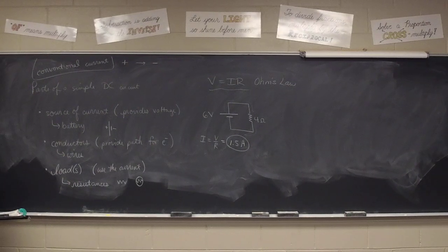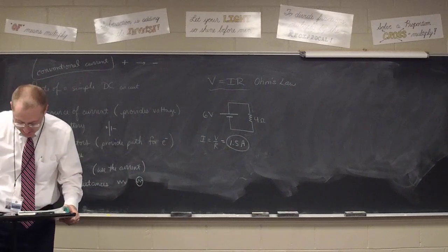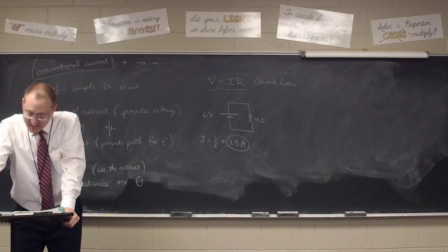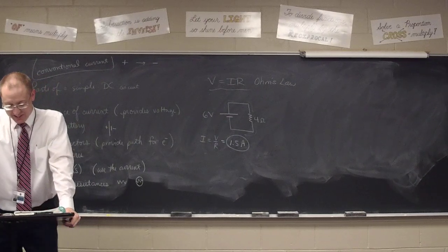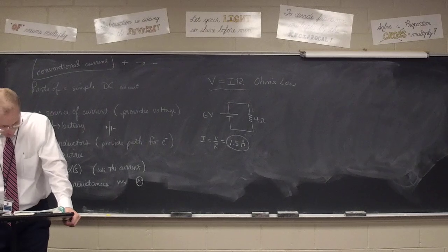A battery is connected to a single unknown resistance. What is the resistance if I is 1.5 V and R is 0.022 A? Okay, instead of saying A and V, let's actually use the words that they stand for because it'll help us remember. What is the resistance if V is 1.5 volts and I is current, 0.022 amperes? There we go, excellent.